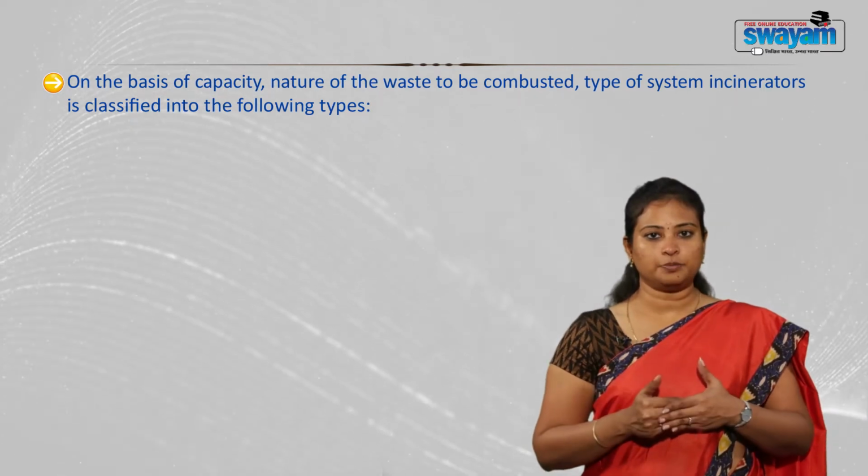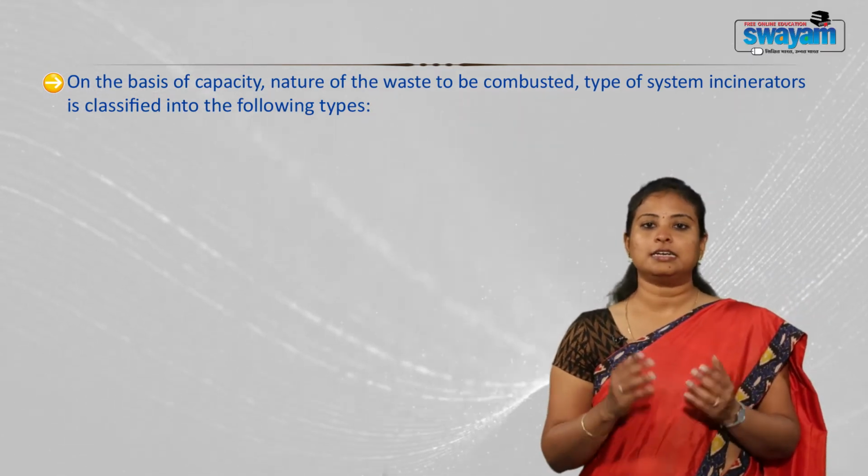To design or select a proper incinerator, you should look into certain characteristics. One, it should be designed to maximize the combustion efficiency of the waste, and second, the heat output that you are going to get. It should always focus on minimizing emissions by balancing oxygen and air, temperature and turbulence. So, these three T's, time, temperature and turbulence, are very important in any incineration technology or process.